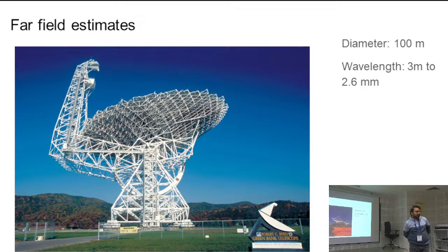Of the order of kilometers. Yeah. So you have to be a few kilometers away when you want to do these measurements. Otherwise, your own equipment will become part of the antenna. And if you calculate the same thing for this, you will find thousands of kilometers. So one very practical consideration is, while measuring these, you have to be in the far field. Just wanted to drive that message across.